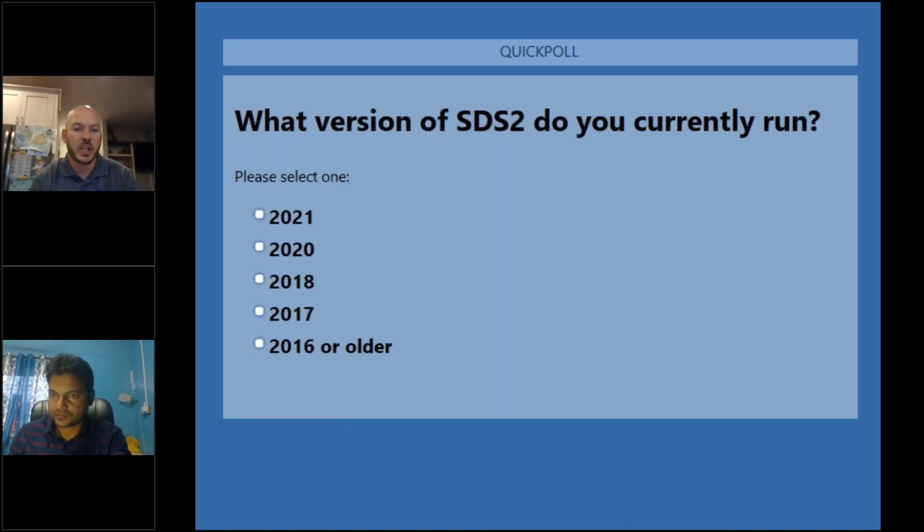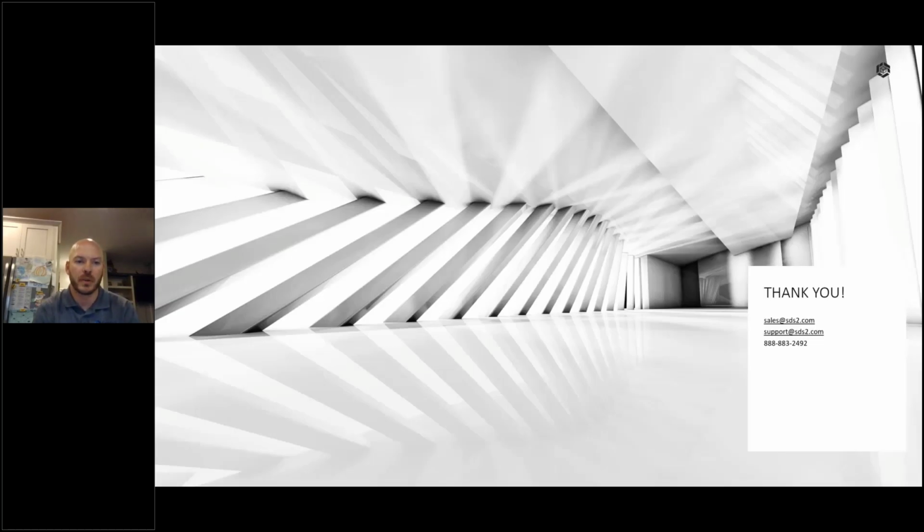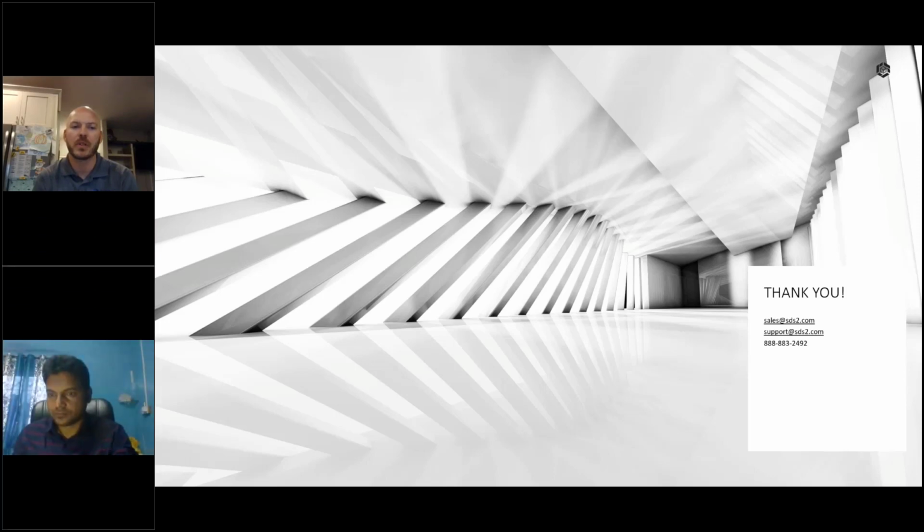So a question here is if the drawings get updated automatically when there are changes made to the model. So it's not an automatic update. So you probably noticed when I created the members, I had to push detail members. So if there's a revision, we just need to go back and click that detail members again.